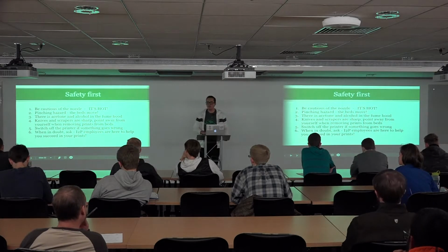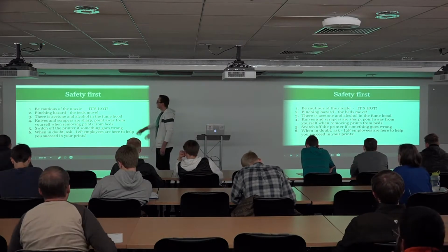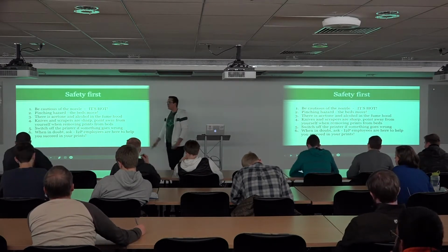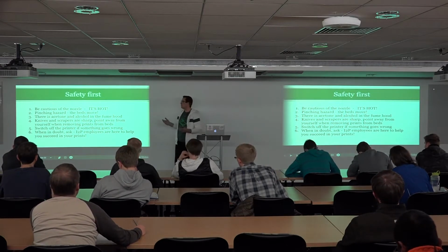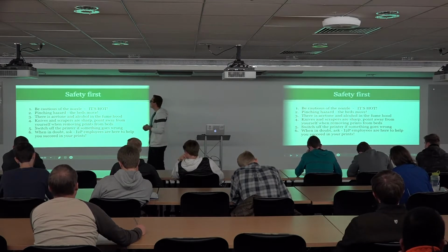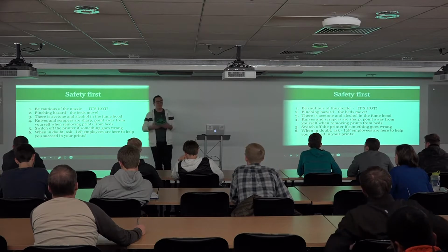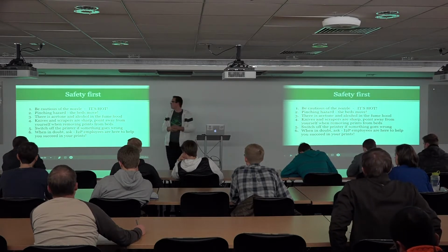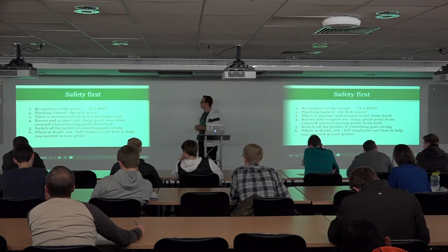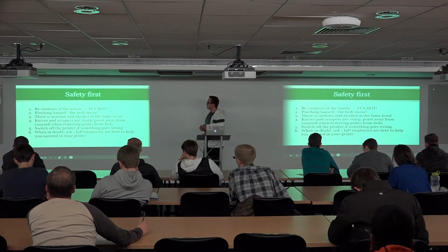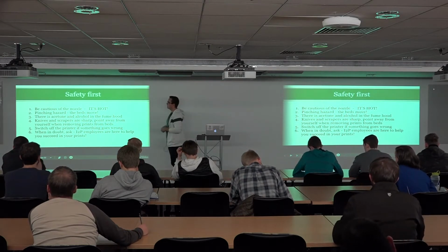And safety first. We mentioned it last because save best for last. So be cautious of the nozzle. It's hot. It's self-explanatory, but we all touch the nozzles anyway just because we're daring and stupid. They're about 230 to 300 degrees Celsius, so that's hot enough to burn you. But hopefully it's not too bad. If it is, we've got equipment for that. Pinching hazards. The beds move, so don't stick your finger between the bed and its races.